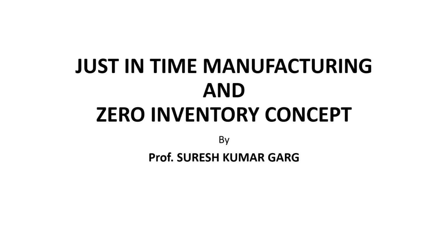This is not only an inventory related policy, it is a very holistic philosophy of manufacturing, but the crux of that philosophy is we should try to reduce the inventories, we should take measures on factors which force us to keep inventory, whether it is due to large batch sizes or large quantities to be purchased, or due to uncertainty in supply, or due to uncertainty in demand, or any other factor because of which we are keeping the inventory, or it can be poor maintenance also, it can be quality related issues also. So, we should take countermeasures on those factors rather than building the inventory for that.